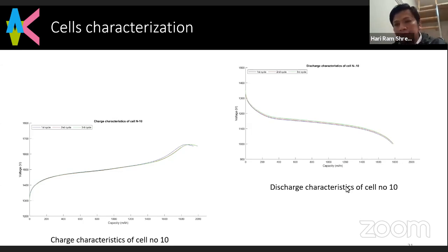So I missed one from the battery side. Do you also have temperature control in the battery? Like if the temperature is lower, then do not charge, or something like that? Is it actively controlled or passively controlled, the temperature control mechanism for the battery? We have a battery heater, and a battery temperature sensor is also included inside the battery box. I think it's passive, not active.